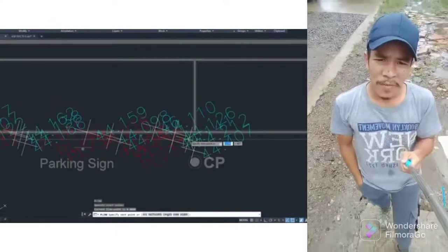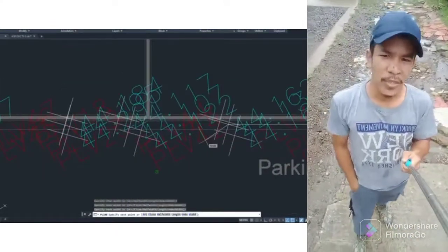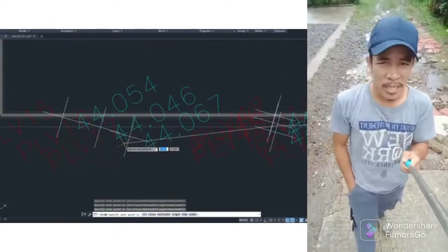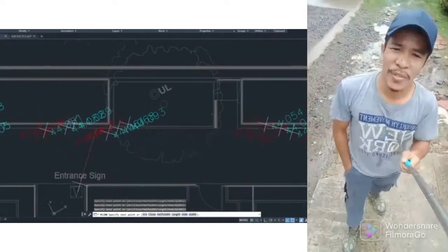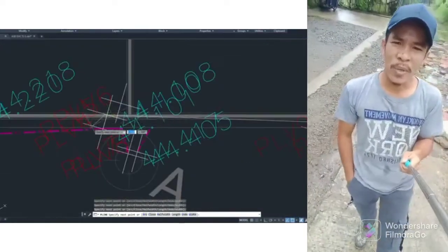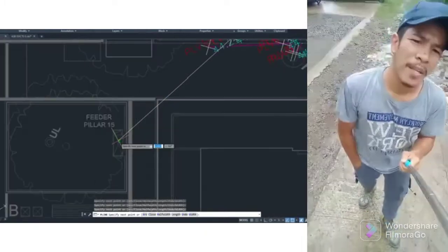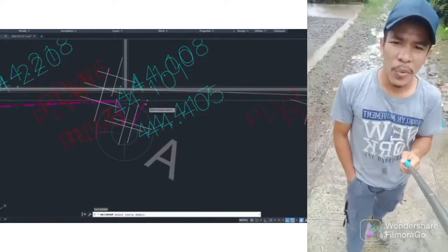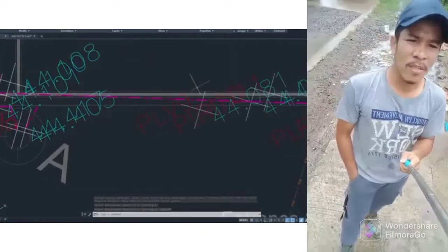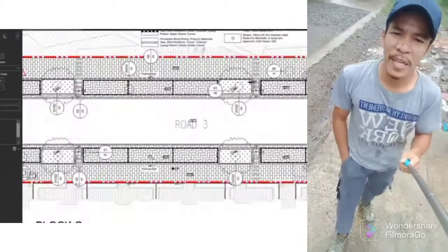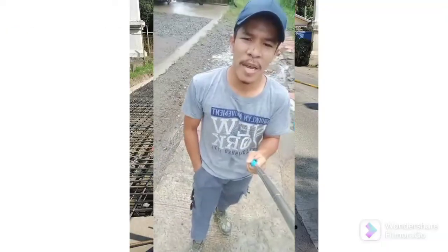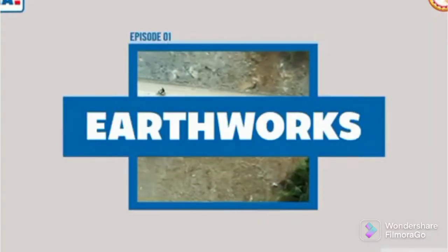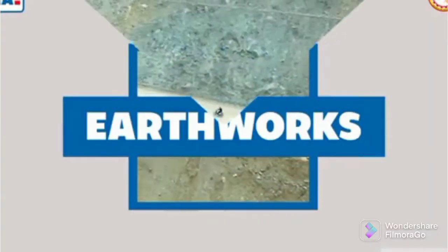The main reason for the setting out, other than to guide the workers as they begin construction, is to ensure the construction remains within the legal boundary. This means there will be no legal disputes later on regarding property boundaries and the right of access.